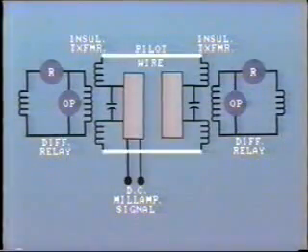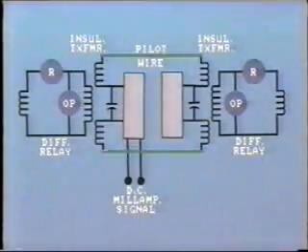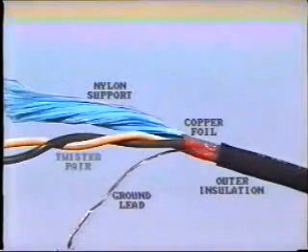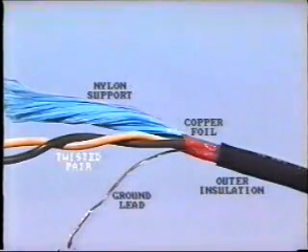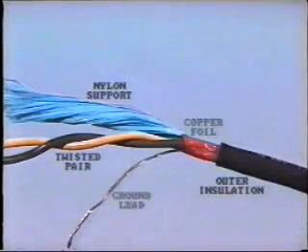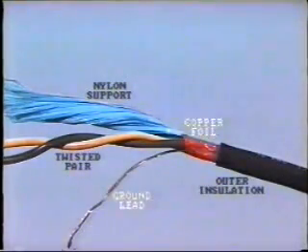The pilot wires are usually quite heavy to provide mechanical strength and keep the resistance between the two terminals at a reasonable level, about 2,500 ohms. The two conductors are always twisted together to form a pair because this reduces the interference due to inductance from nearby signals and external voltages, such as the power line itself. The pilot wire is often buried in the ground and protected by shielding, which will, of course, be at the potential of the surrounding earth.